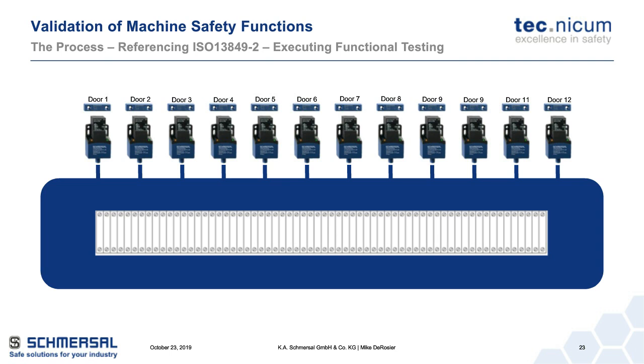So maybe that's the easiest place to do your functional testing, but then what type of testing are you doing? When you do an electromechanical switch like that standard key interlock in the previous example, you're doing those opens and short circuits. Well, what if you have switches like these, which are actually more electronic, like RFID type of safety switches? It's not as straightforward to do some of the same type of testing, but it's similar. You can do short circuits on OSSD outputs because the switches are supposed to detect that and still provide your shutdown. But you have to determine, right back in your design and your analysis portion of it, what is the actual test plan? Meaning, what faults are you going to introduce, and how are you going to introduce them as a result?